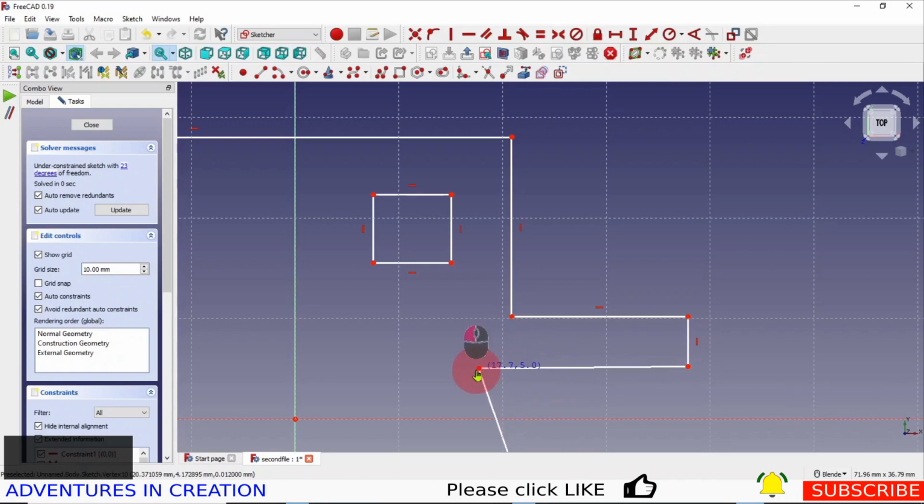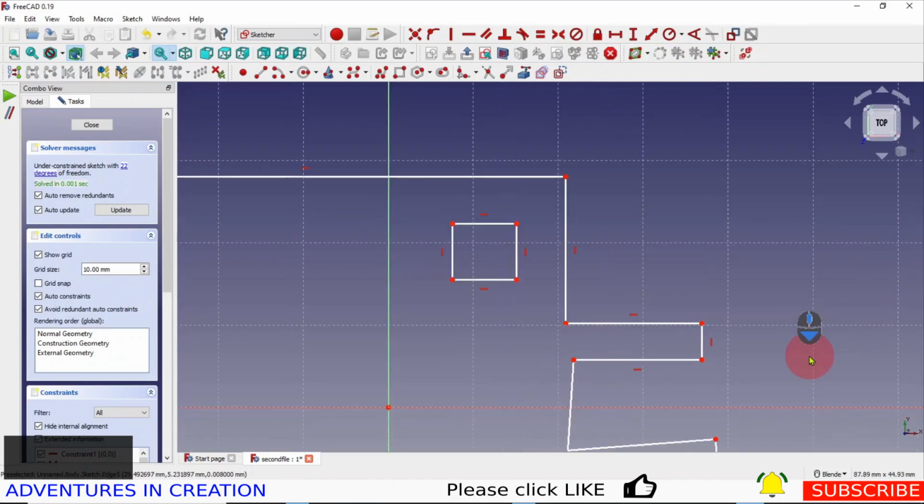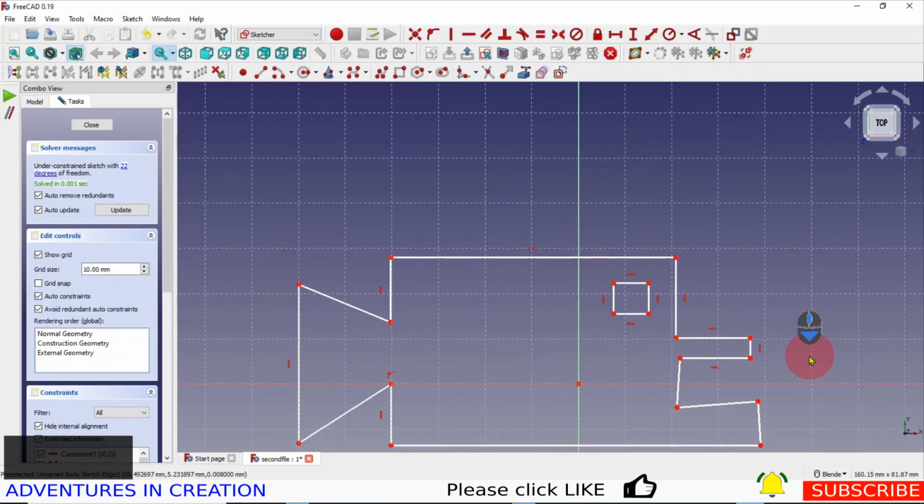But on our sketch, it should be horizontal. So I'm going to touch that line. I go up here to the horizontal constraint. I click that. And now this line will move as a solid line because it is horizontal. Equally, this line and this line don't have those horizontal or vertical constraints.